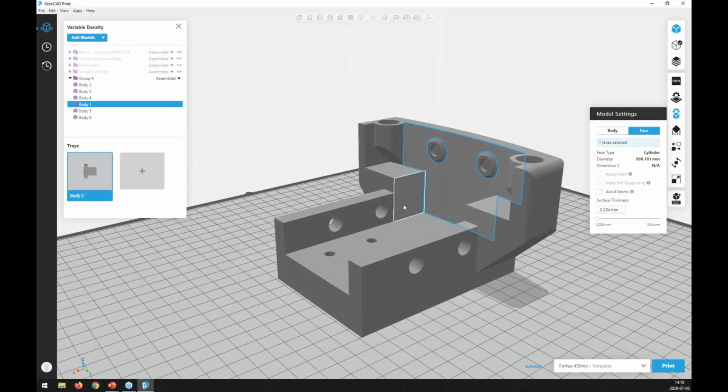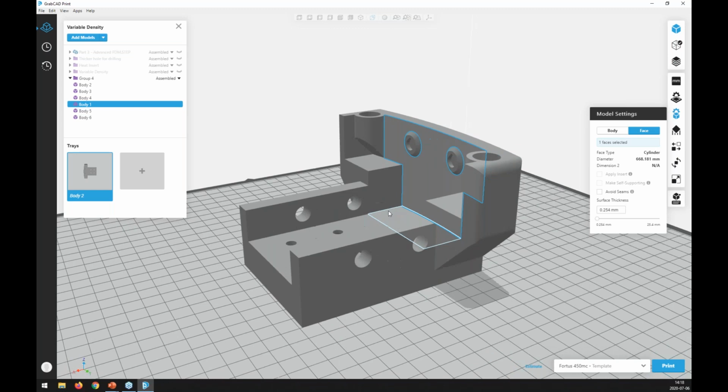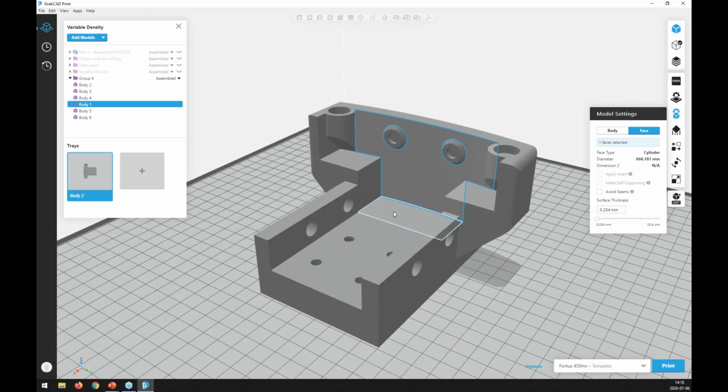So the first thing we are going to do, you see in the last session, we spoke about these vertical holes here, and that we can make them self-supporting by adding a diamond shape. So it's okay when you have 2 or 3, 4 holes. It's quite easy to do that in CAD, but if you have multiple holes and need to make them self-supporting, maybe you can leave this task up to the operator in the preparing software to do this for you.